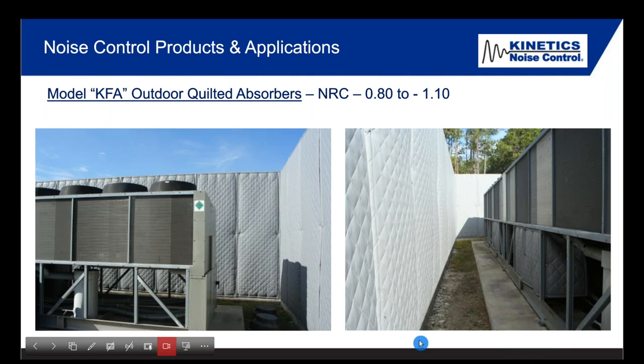You can also use an outdoor version of that quilt. We're always looking at a budget. You are either retrofitting noise control, thinking, wow, we didn't plan that money in there, but we're getting noise complaints, or it could be a new design. In a retrofit, if the budget is limiting, then you can use this outdoor quilt. Put furring strips behind it, and you can line the walls with it.